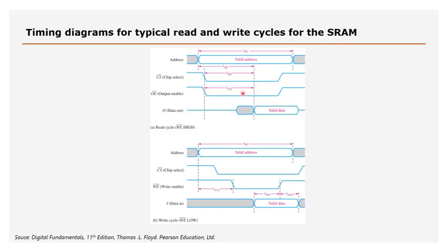In a microcontroller like the 8051 that we use, once you've pulled the chip select and the output enable, it normally takes a microsecond or two before we start reading the data, which is way more than enough time for the data to become valid. So it's not really a big issue.